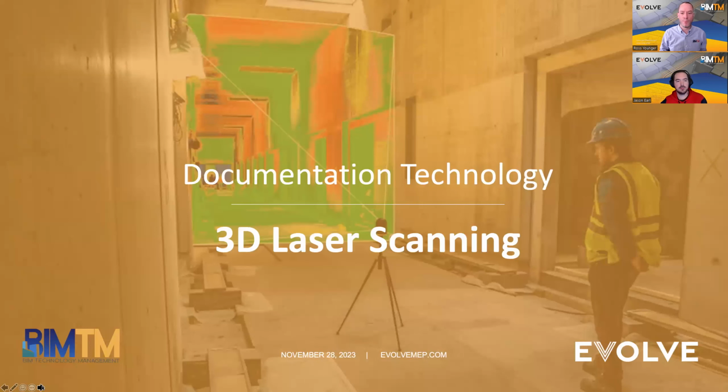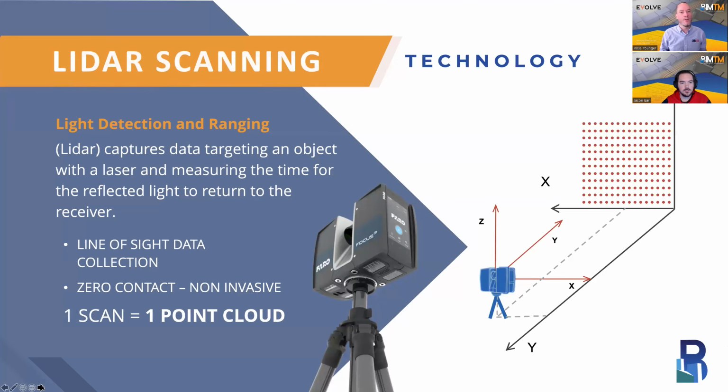So the primary technology being used right now is 3D laser scanning. 3D laser scanning, also referred to as LiDAR, which is light detection and ranging, basically covers the entirety of a subject with individual point measurements, each of which represents an XYZ coordinate. So, think of a laser measure. You point that out, it extends until it hits an object, and then it reflects back and gives you that distance. That would be one point in a point cloud.